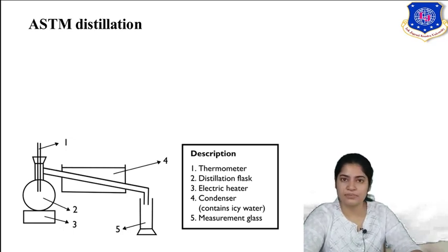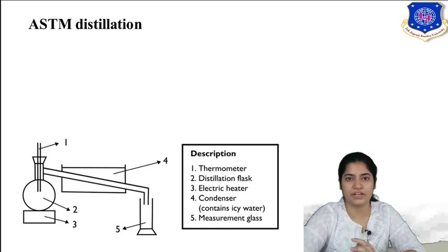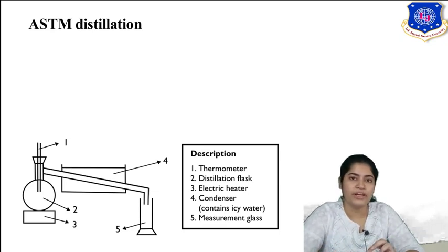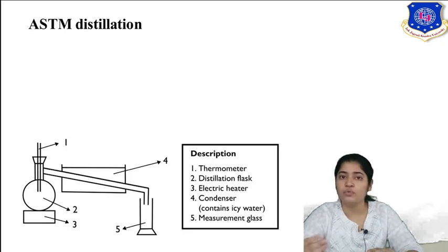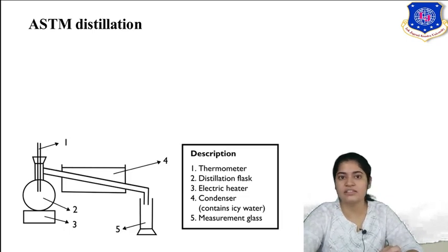The difference between TBP and ASTM is that now you are not providing a fractionating tower. You are not providing a packing material. So there is less contact between vapor and liquid, plus you are not providing a reflux condition. Well, actually what is reflux? As a revision of your distillation, the more volatile component which vaporizes, travels, is condensed and liquefied. And reflux is when you take a part of that distilled liquid and transfer it back into the fractionating column. So that is reflux.